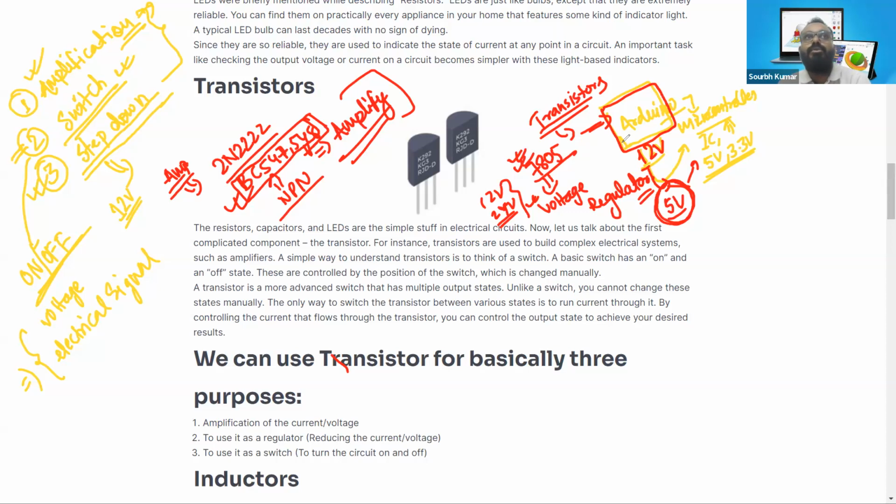Suppose you are going to use servo motors in your application, then you cannot drive 6 or 8 servos using the Arduino board. You have to utilize some transistor or IC based regulators or controllers, we can call them controllers, to help you maintain the proper energy flow, like the current and voltage, to power up the heavy output devices.